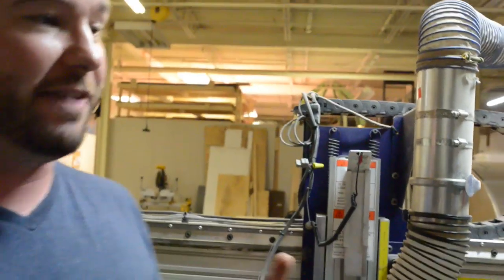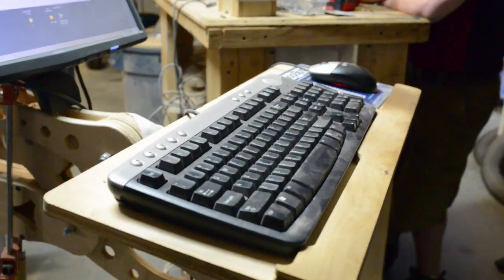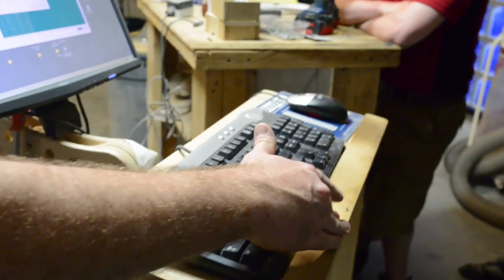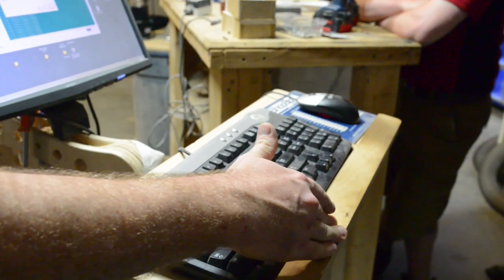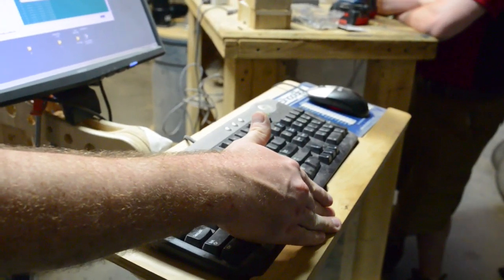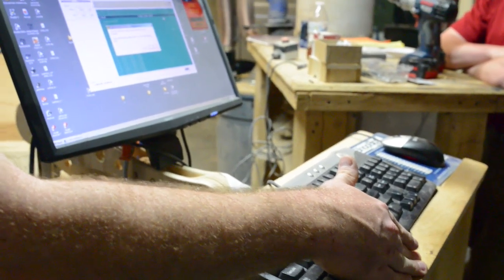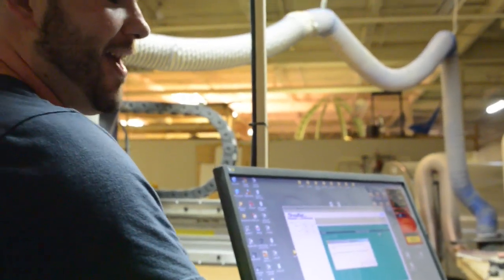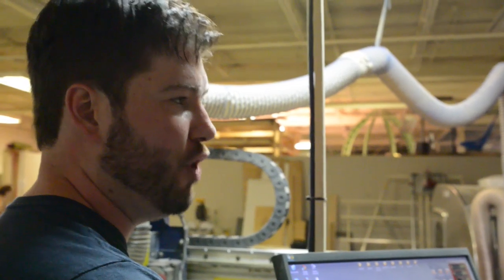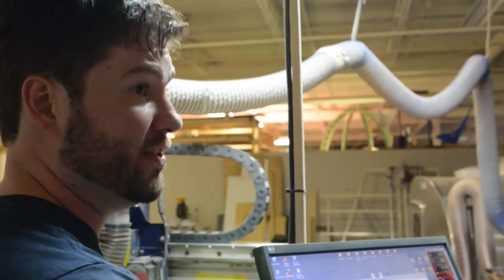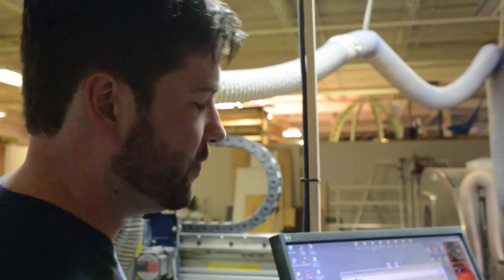And once again, the oh shit button is space bar. Even now, I've done this a lot of times, the very first 10 seconds of doing the cut, my hands are right here. Because if I'm getting a little too close to a screw, carbide is not harder than drywall screws. It will destroy your $50 bit immediately. So plan out your screw holes very, very well. I have ruined many bits because of 'that's good enough, close enough.' No, make sure you know exactly where your screw heads are. So once again, spacebar, the oh shit button.